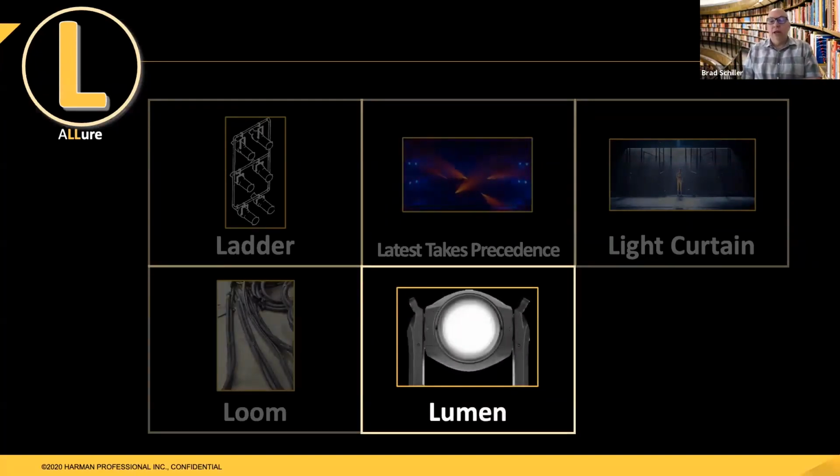Lumen is the measure of light output from the source itself. It could be directly from a light bulb or the output from the front of the light. So lumen is the measure of the light output from a source. And it tells you how much light is coming out. And it can be measured in one of two methods, either by looking at where it's shining to, not what it's shined onto, and using different calculations with light meters, or it can be put into a big calculating sphere in which they measure all the light that's coming out of that fixture. And lumens are the general basis that we use to define how bright lights are.